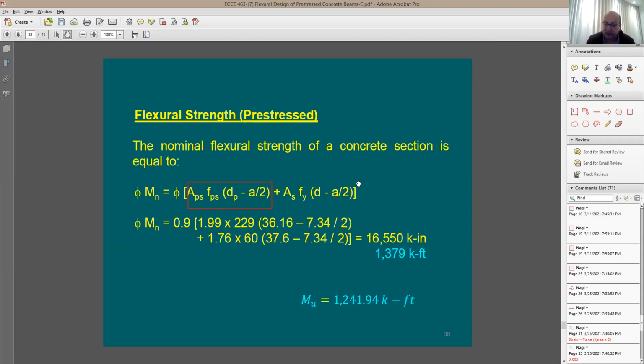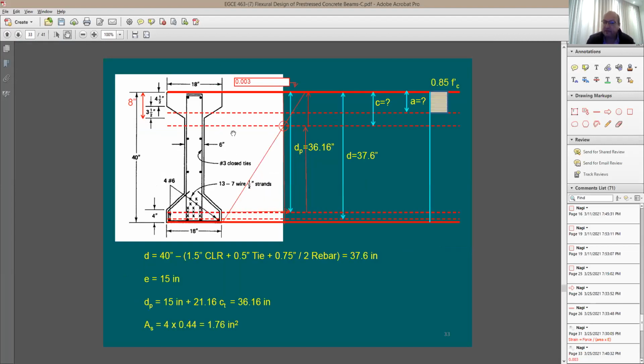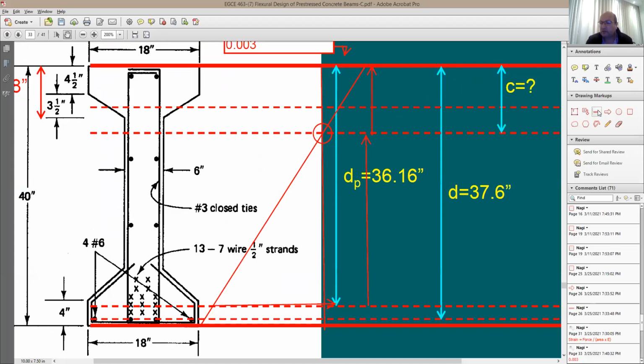Now, in your case, you're not going to be exposed to something like this because you cannot do this by hand. Just think about it this way. The way the software is doing it, it cuts this into slices. It is taking the concrete beam and cutting it into very small slices like this. It's going to be, let's say, 1/2 inch, and you can decide on the height of each slice, right? And then when it comes here, it's also going to be cutting this. Look at this. It's going to be cutting it like this, right? It's going to be very small segments, and each segment is going to have a different width. Does this make sense to you?